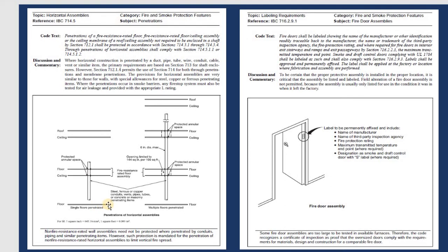So even if you have the design ready, you need to go with the code to make sure what kind of construction group it is, what the special material is for smoke and fire, and where the position is in the building, vertical or horizontal, and they need to submit the fire rating for that.